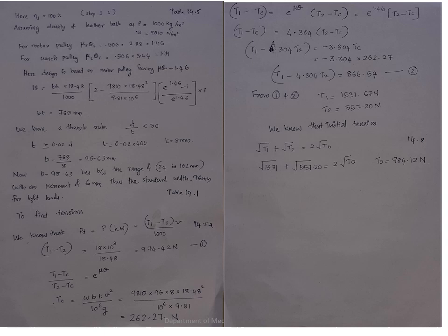In belt design, we use a thumb rule: b by t is less than or equal to 50. Please consider this as less than or equal to 50. Then t is greater than or equal to 0.02, and substitute that value. You will obtain the value of t from this equation, and that yields b is equal to 765 by t. Using this equation you can find t, and substituting t here you find the value of b.